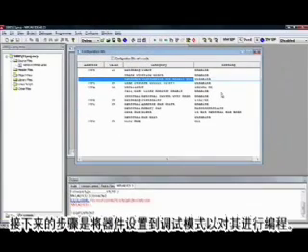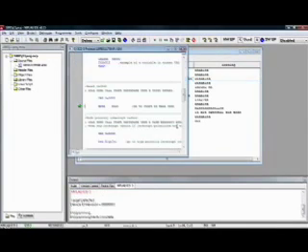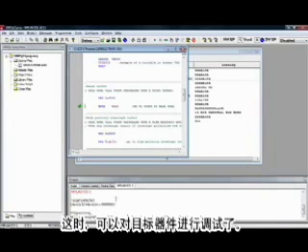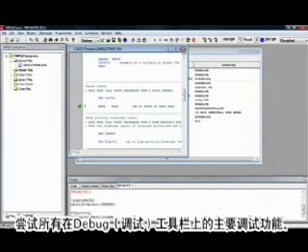The next step to getting the device into debug mode is to program it. Press the Program button. Notice that MPLAB ICD3 status is again displayed in the output window. At this point, the target device can be debugged. Try each of the main debugging functions exposed by the debug toolbar.